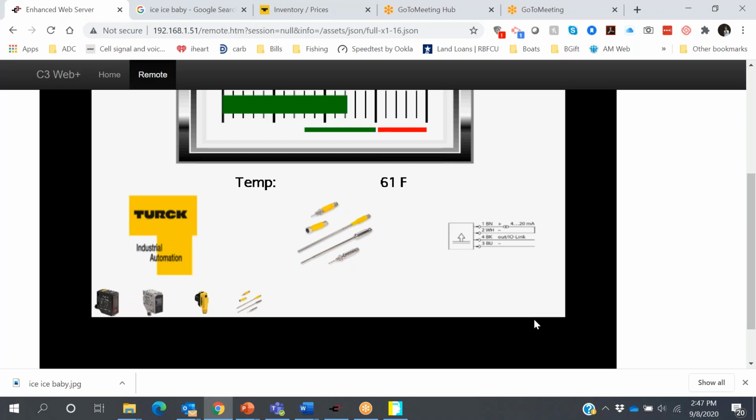So if I connect it to this block, it's going to fire up and tell me this is in what we call dual mode. You can see here with the 3 LEDs across the top, it's telling me what mode it's in. This particular mode gives me a percentage readout. So in this application, that's what I want. Maybe I'm sensing a clear object or something like that. But in the other application, I want it to be more of a laser distance sensor. So I'm just going to unplug it from this IO-Link master and plug it into port 3 of this one.